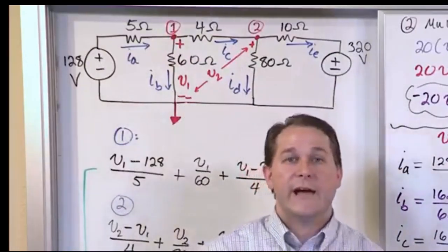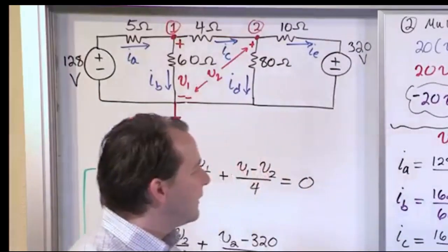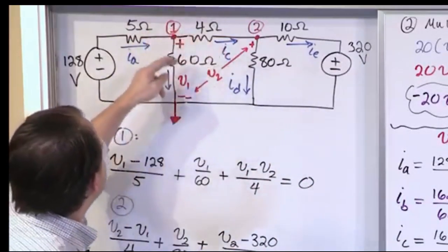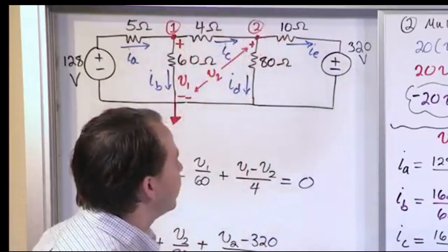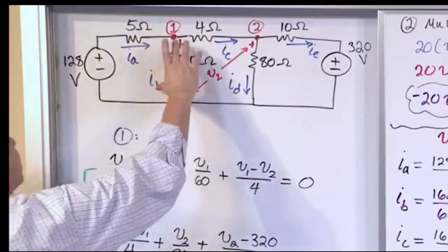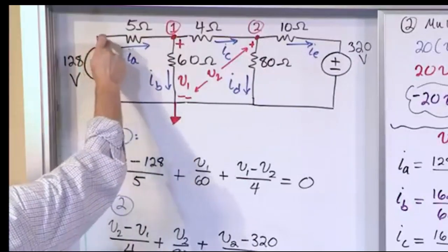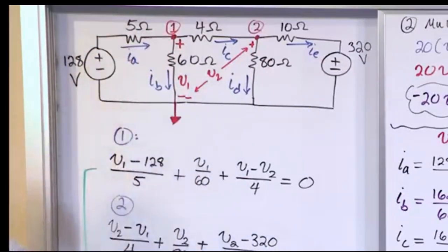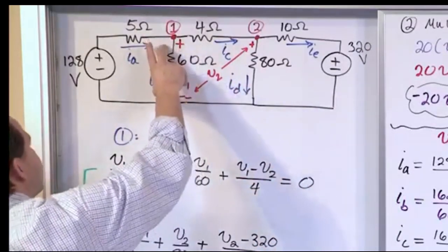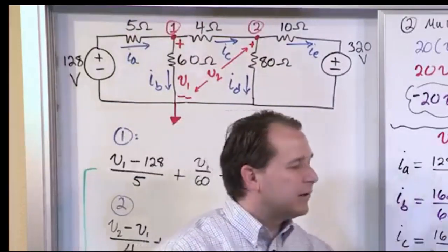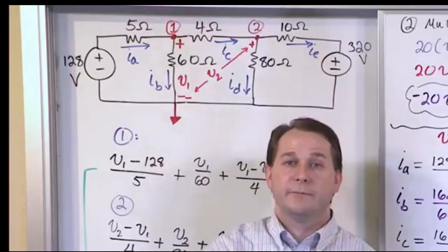and then again, we've said it in the very first section, when you have V1 and V2, when you have your node voltages, you can find anything else in the problem. It's a good example of showing you how. Once you have the node voltages, you can just do subtraction and find the voltage drop across any element, and then you can find the current. Once you know what the node voltages are, then you can say, okay, they're saying IA goes this way, so I'm going to take 128 minus this and figure out if they're right. Turns out they're not right. It was negative. They're saying IB goes this way. Okay, I have a voltage drop there, and so on. And you apply the sign conventions that we've been using to help figure out the subtraction business.